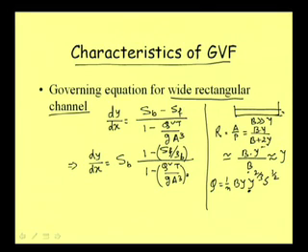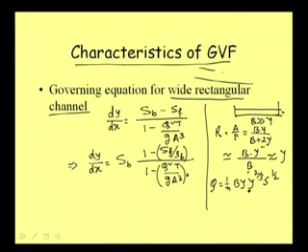Now, when we are writing this expression for gradually varied flow, then we know that as it is gradually varied flow, at each and every section it will not be the uniform flow depth. Rather, say, if in a channel uniform flow is flowing like that, this is the yn, then somewhere here it will be rising like this. Say this is our bed and it is rising like this. So at any section this will be depth y, it is not the uniform flow depth. And when we write this resistance flow formula, this is nothing but the resistance flow formula. We can write Chezy's equation, Manning's equation, all those resistance flow formulas, and we consider this as valid.